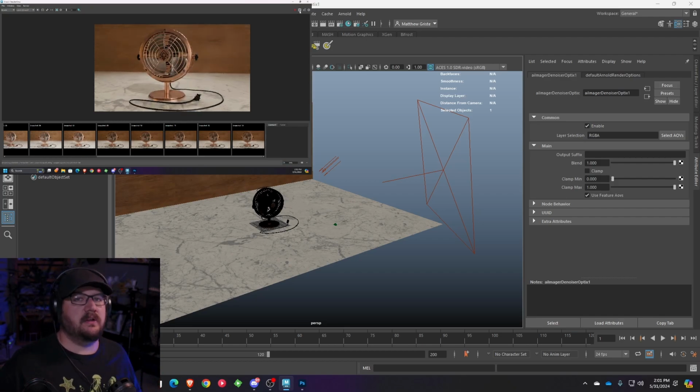You can see the image comes out incredibly blurry. It looks horrible. But as you render through, it refines, it gets better, it gets cleaner. So we're going to let it run through its thing. This also improves our render time just a tad bit, because what it's doing is it's using logical cores on your GPU to actually go through and refine the render instead of trying to post-process everything with samples.